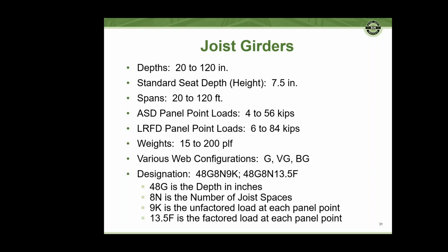Joist girders, a quick summary page here. Those are available in depths from 20 inches to 120 inches. The standard bearing seat depth is 7.5 inches, although there are cases where it will increase, and we'll get to that, I believe, in the next slide.